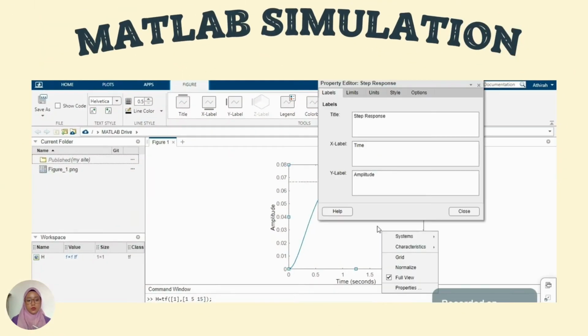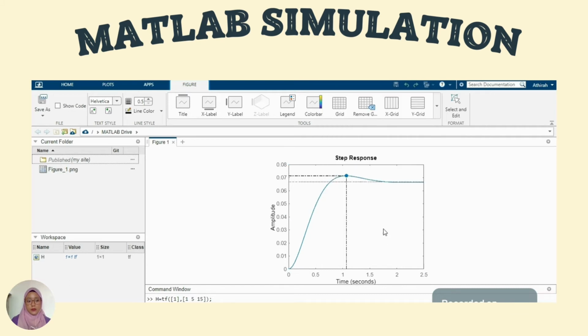After the graph is shown, we need to find the peak time and the settling time. How? We can use this. We just right click and choose peak response and settling time, and then the graph will plot where the value is.